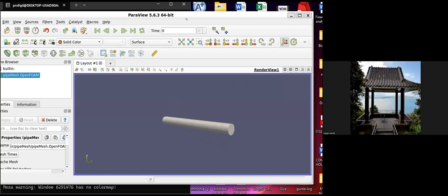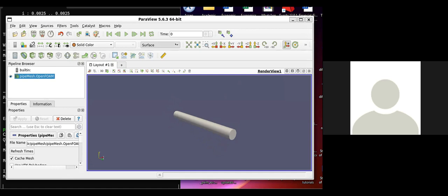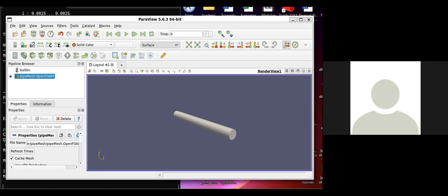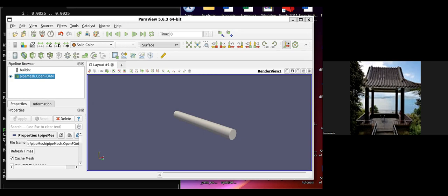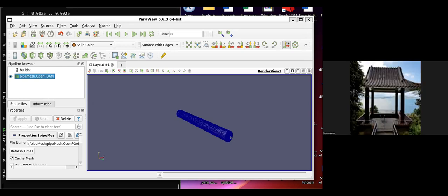Okay, let's see. So, make it bold. Okay, now show surface instead. Can you see surface at the top? Click on it, and then what do you see? 3D glyphs, feature edges, outline, points, surface, Gaussian. Yes, surface with edges. Show that and let's see. Apply. Yeah, so that's your mesh. Zoom in.